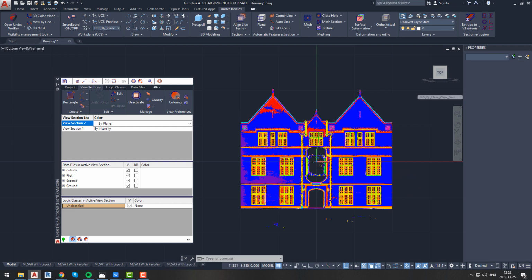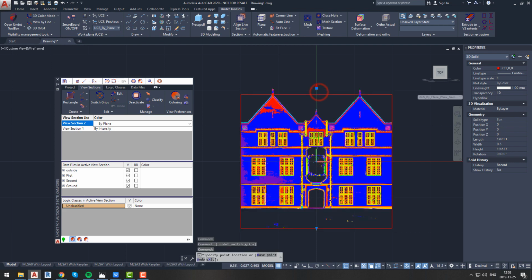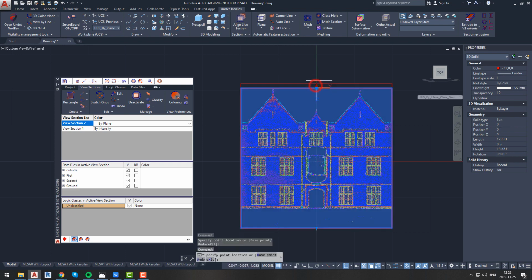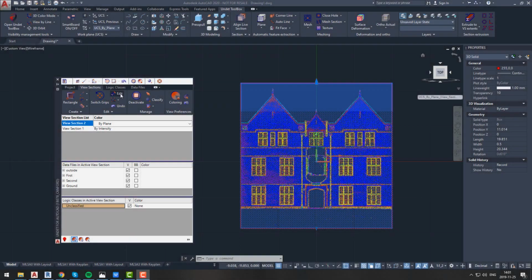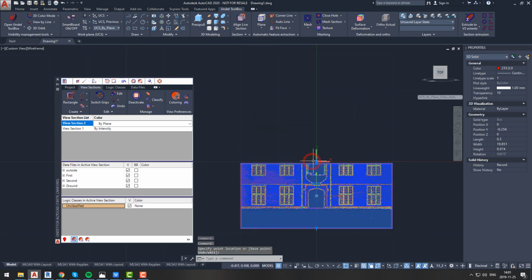The other way to make the indicator green is by adjusting the active view section size and allowing Undet to make calculations and determine if the point count is smaller than the max visible points count. We recommend adjusting the size of the view section and allowing Undet to determine when to show preview points and when to show all points. After our clipping box is small enough, Undet will automatically turn the indicator green and we will see all of the points.